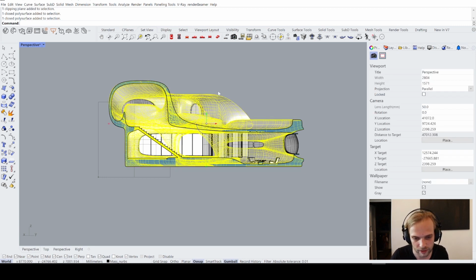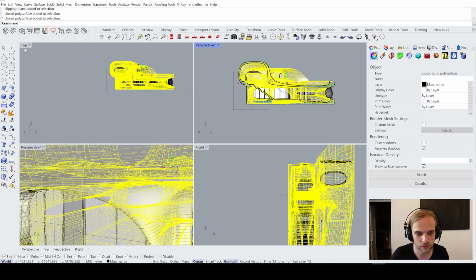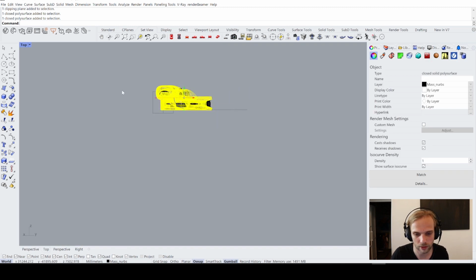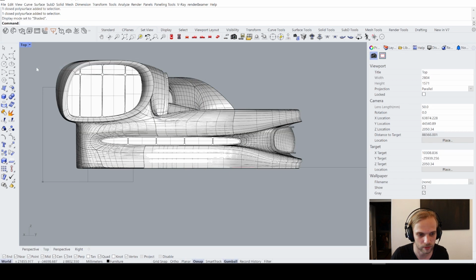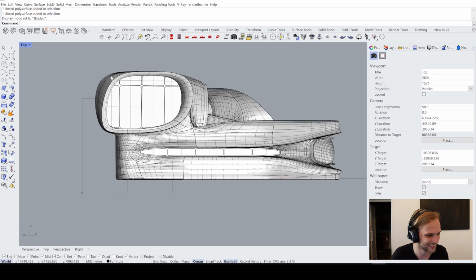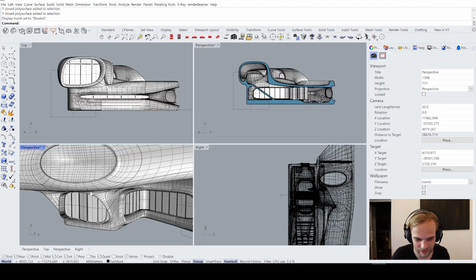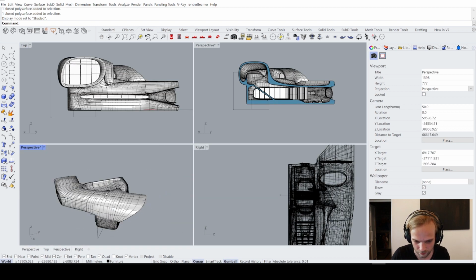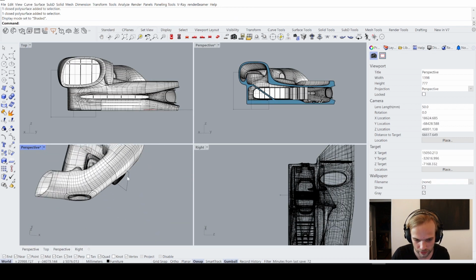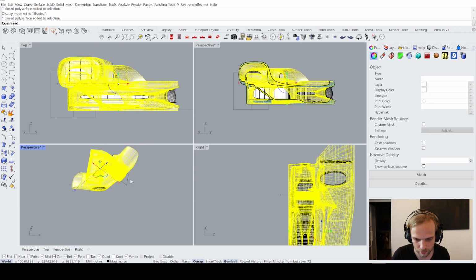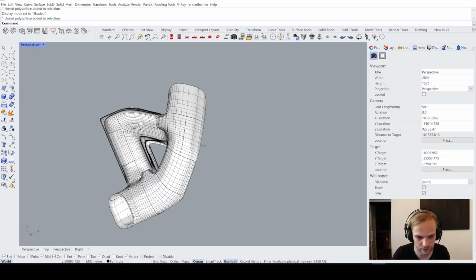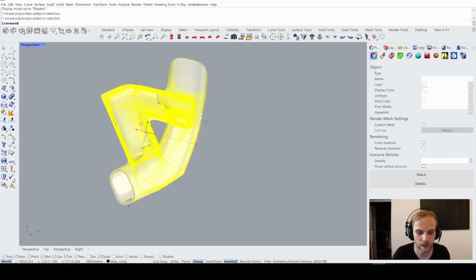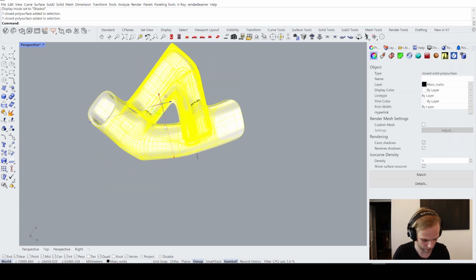So I'll select the form. I'll go to probably the top view. Well, our top view right now is also the same view right here. So let's just see which one can we use. Maybe this. This perspective view seems fine. It's not being used. So I'll just select it. I'll type in contour.